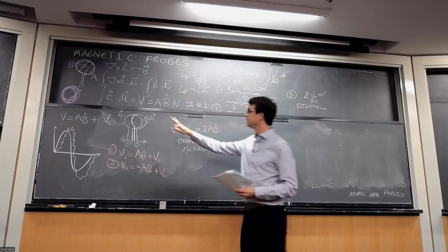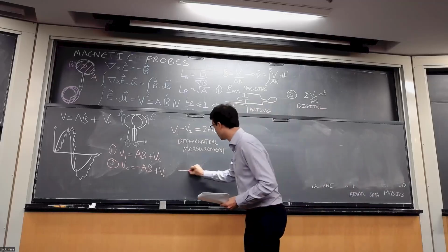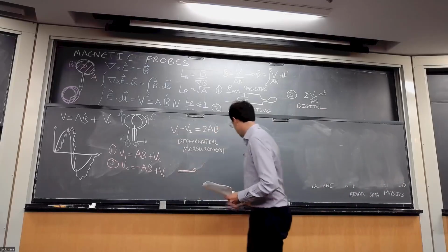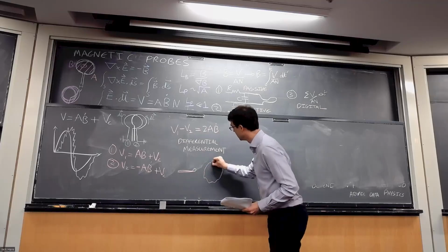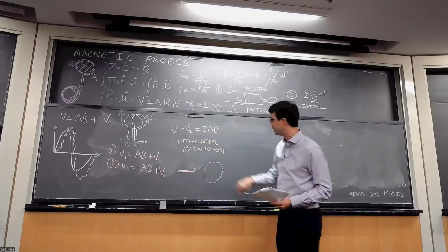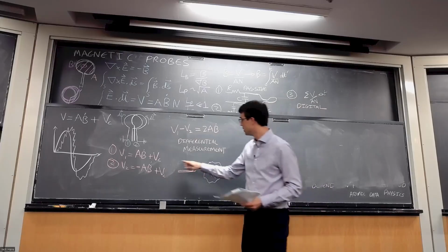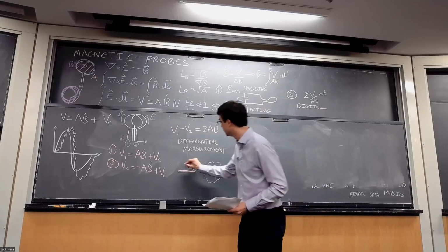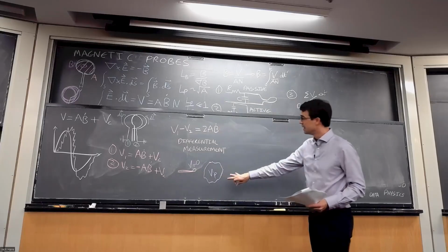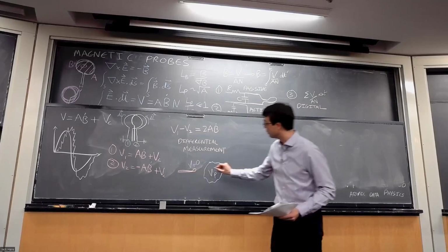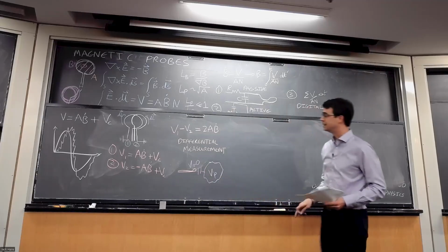So if you're asking where this capacitively coupled signal comes from, just imagine having your B dot probe like this, and there's some plasma floating over here. This plasma may be at some potential V plasma, and your probe may be attached near ground, so it's floating at close to V equals 0. But you can see effectively there's going to be some capacitive coupling.